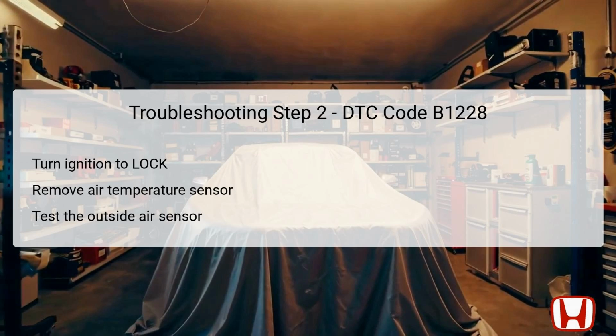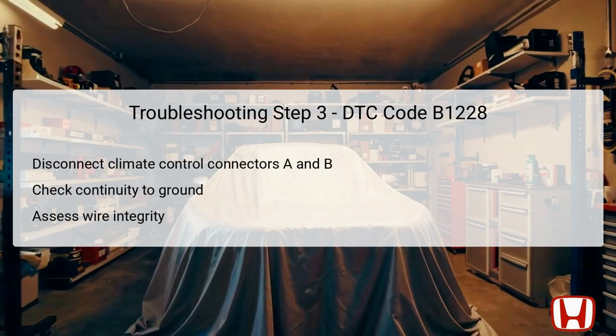optimal climate control operation. Disconnect the climate control unit connectors A, 28P and B, 12P carefully. Testing the wiring integrity is crucial, as it can help pinpoint if a short circuit exists between the climate control unit and the outside air temperature sensor circuit.